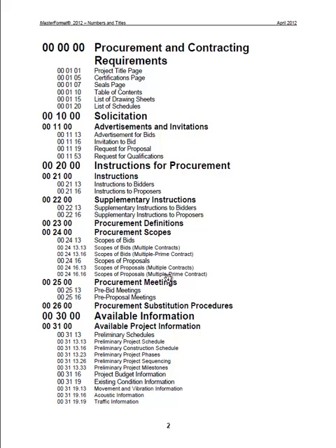All the different contracts are listed out here. Pre-bid meetings. Anytime we have a large project, we may want to have either a mandatory or non-mandatory pre-bid meeting that gives the contractors an opportunity to walk the site, look at the drawings, and ask any questions that may allow the designer to make a few minor changes. Pre-proposal meetings are also included in here.